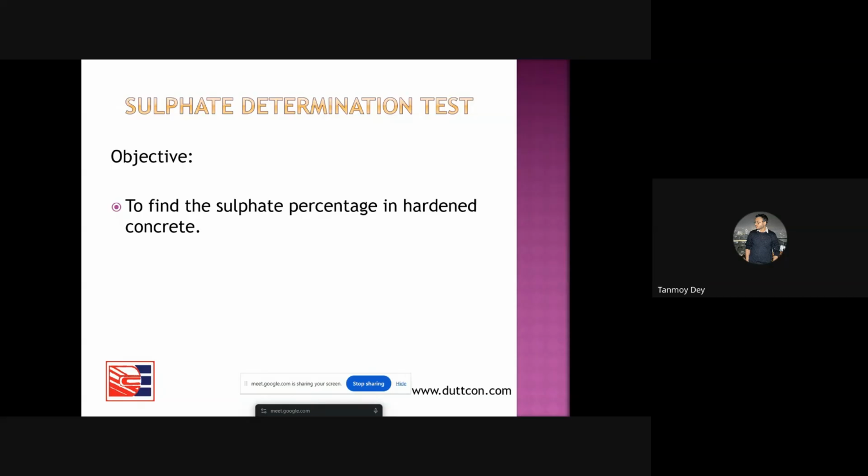So this is more or less a common method in other atmospheres. Say the atmosphere has some chemical plant producing H2SO4, producing HCl. So penetration of sulfate and chloride is also important. What will we do? We take some sample to the lab. This particular sample is tested for pH, chloride content, and sulfate content. This is a destructive test, not an NDT test.